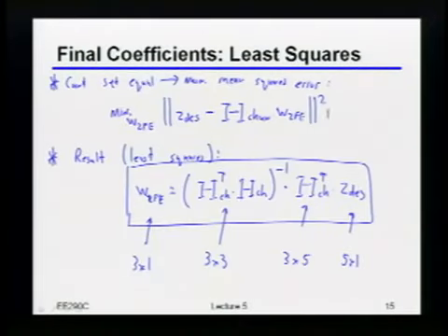The reason for that we'll actually talk about next lecture. It just has to do with the fact that when you write things this way, what you're intrinsically assuming is that the residual ISI looks kind of Gaussian, meaning its distribution looks like the distribution of the noise. But if the residual ISI does not look Gaussian or has some very different statistics, then this is not the BER-optimal way of handling it. Okay? Like I said, we'll talk some more about that probably next lecture. But from 20,000 feet, that's the reason why there's a distinction there.